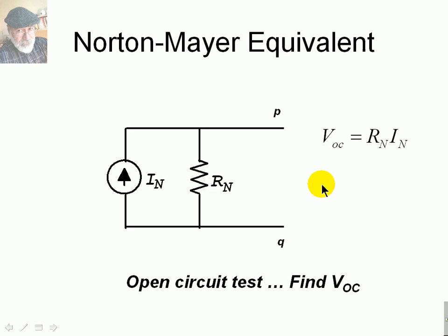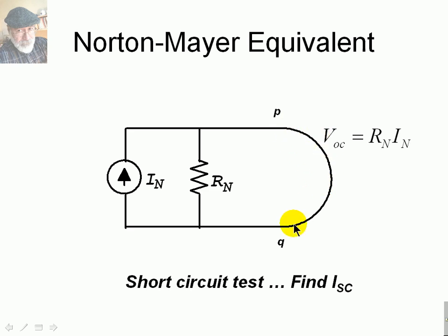How do we find another equation? Short circuit. Short circuit the port, and let's compute that short circuit current in this wire. My question to you is, what is the current in this resistor? That is an R branch connected to the same node on both ends, so the voltage drop across that resistor is going to be 0, so 0 is going to be that current.